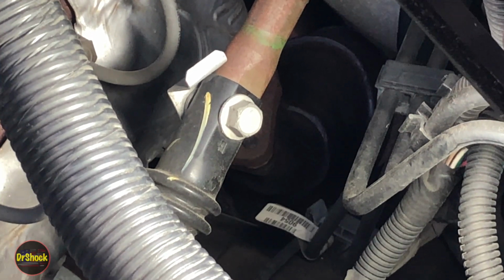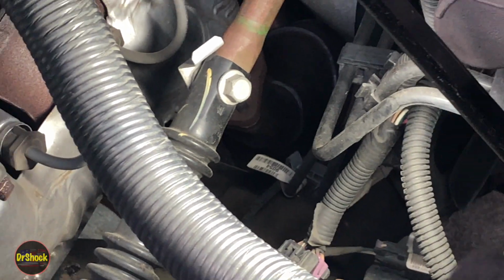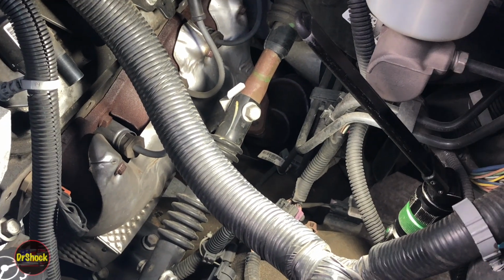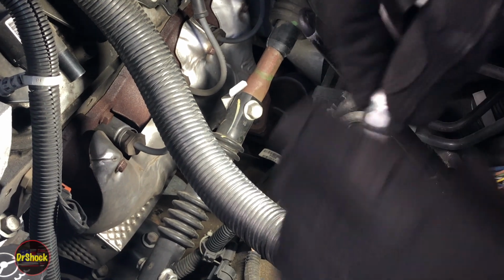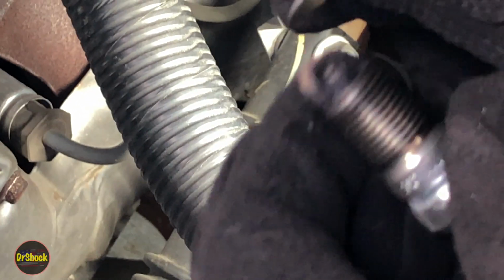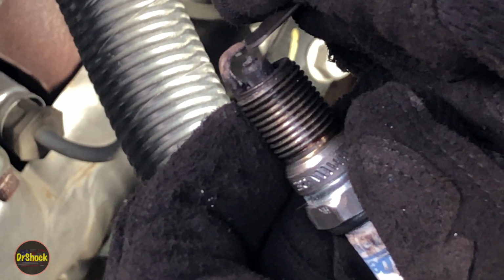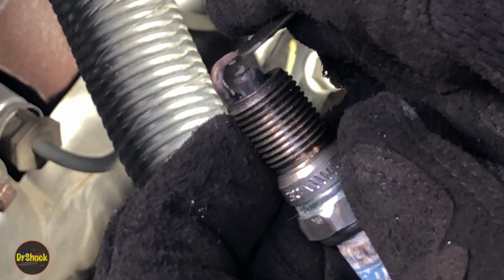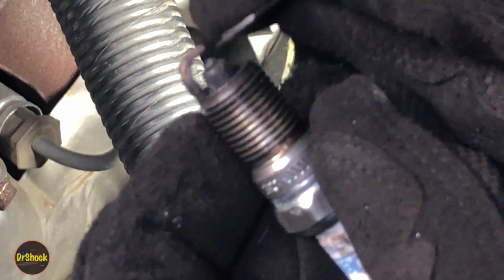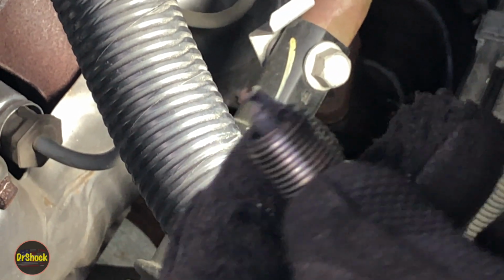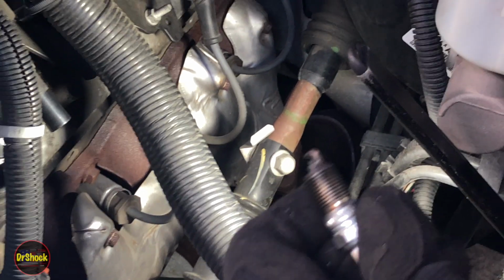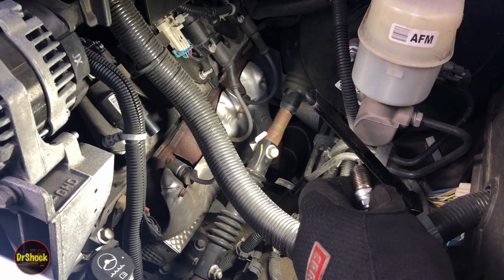Put this guy back in the box. We'll go grab our used plug. We do the same experiment, but you don't have to even stick this in there. Right? Just touching right at the top. You can see there's a massive gap. This is closer to a 60 thousandth gap. So is that the problem? Well, again, that is a problem. Don't know yet if it's the problem.